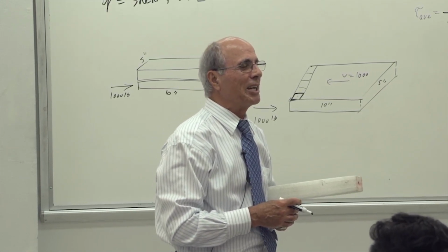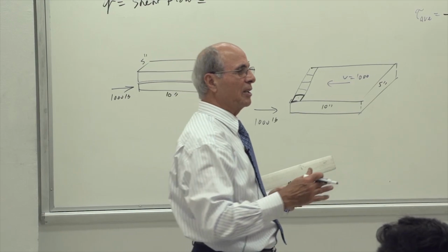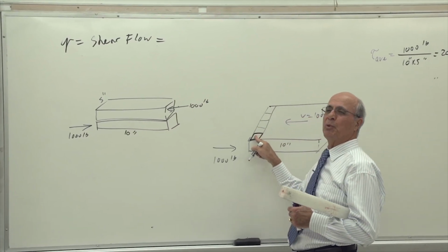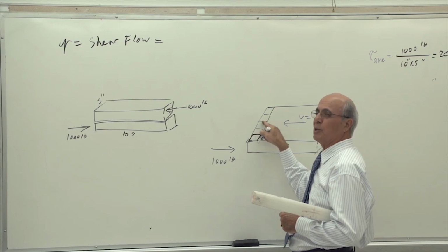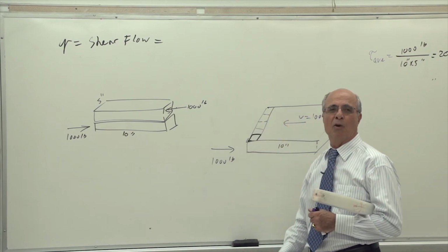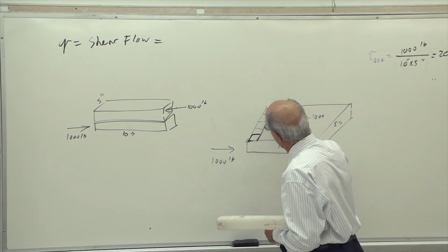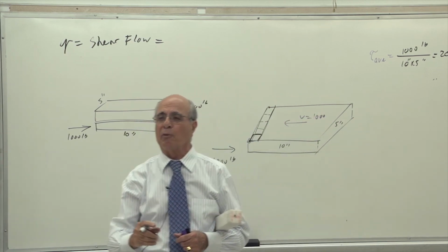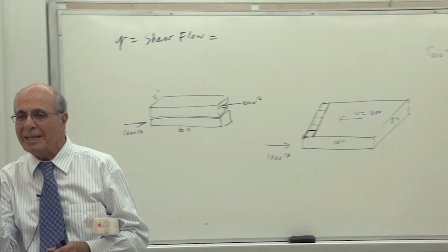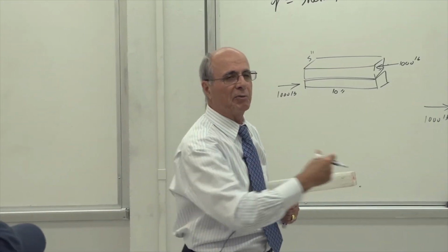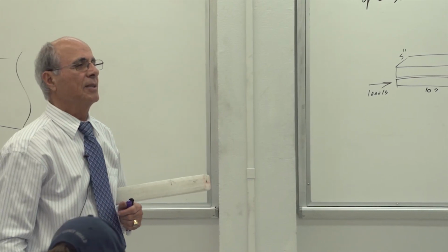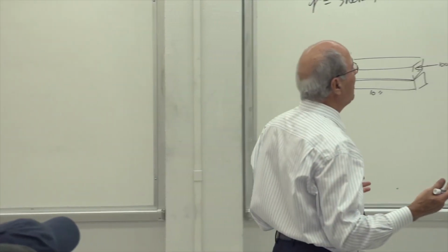Yes? Therefore, that's exactly the point here, guys. Suddenly, this is very simple. 1 square inch is 20. Yes or no? 20, 20, 20, 20, 20. That is 100. That's the amount of force in that one strip. We call it shear force. Write it down. The amount of force per 1 unit length of the beam. If this was a beam, that would be 1 inch or 1 millimeter. Yes or no? Yes? How do we come up with the formula?